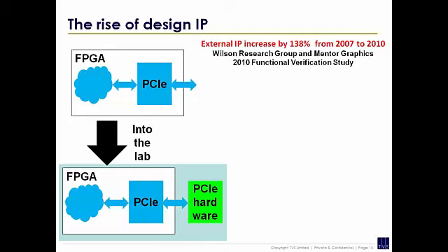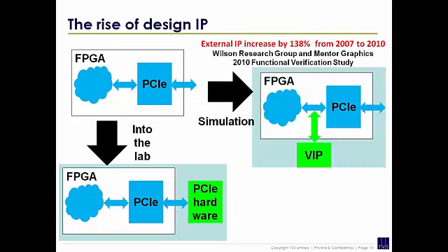It becomes very hard to debug, and you don't know if you've got all the PCIe protocol covered. So what we did with them, using the simulation environment, we said, why are you verifying that? You don't need to. That's given to you. This is called verification IP. It's an Altera FPGA, and there's an internal bus on it. You can generate transactions onto that internal bus as if they came through the PCIe, so you can verify the design directly without going through the PCIe.